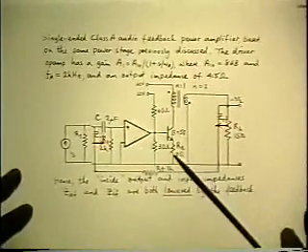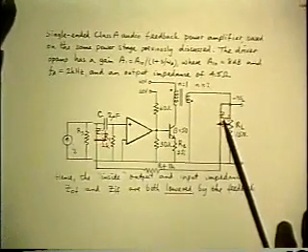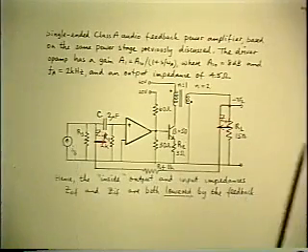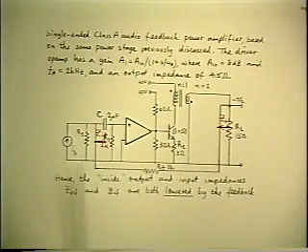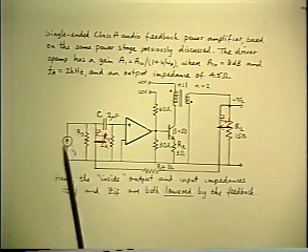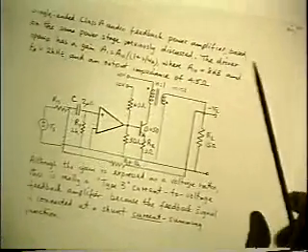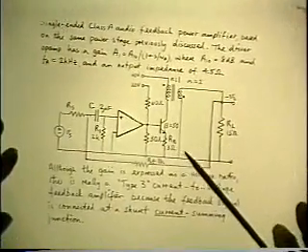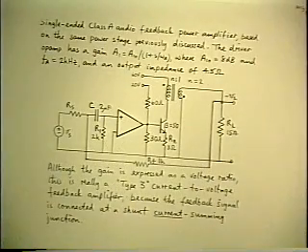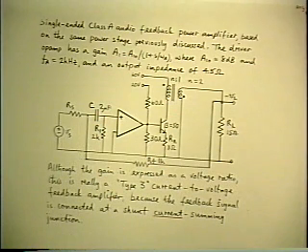And you see that what determines which of the 4 types the system is not how you identify the source or the load. What makes the difference is how you connected the feedback. So regardless of whether I use Is as the explicit source or whether I use the Vs, which is what I in fact did, it doesn't change the fact that this is a type 3 feedback system, because I'm not changing the connection of the feedback when I change the representation of the source.